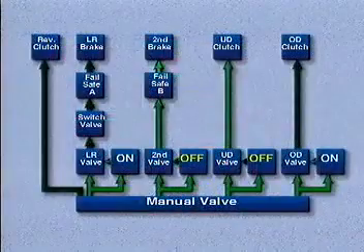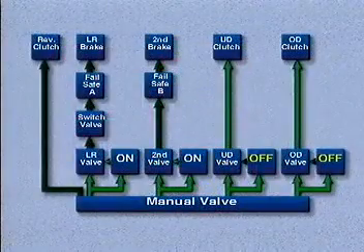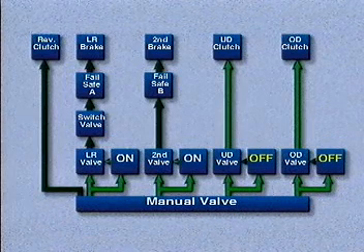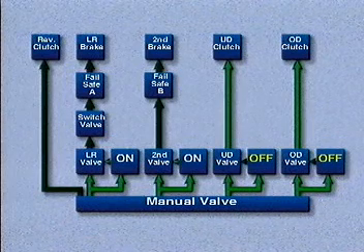As a result, the planetary gear set locks and turns as a unit to produce a 1-to-1 gear ratio. During the shift from second to third gear, the second brake solenoid goes from off to on, and the overdrive solenoid goes from on to off. All other solenoids remain as shown.